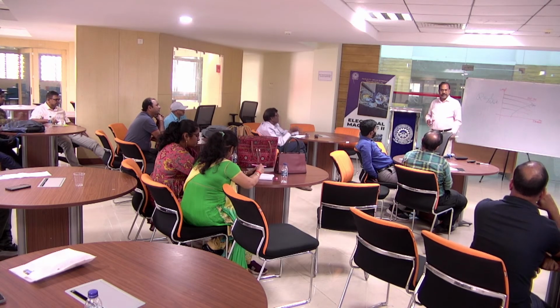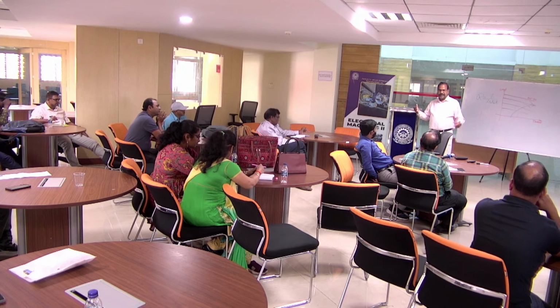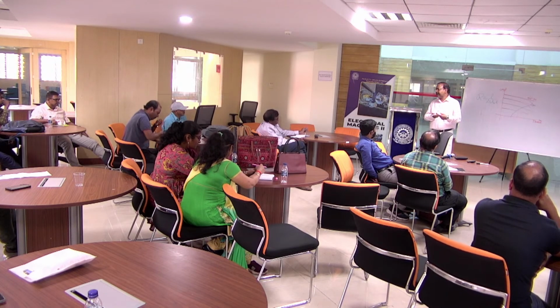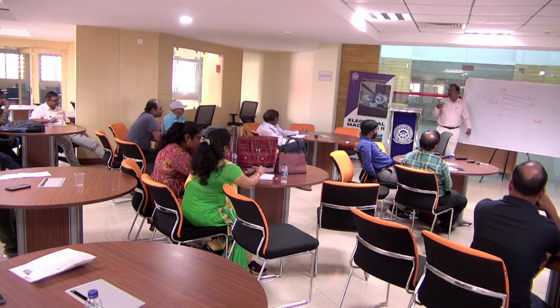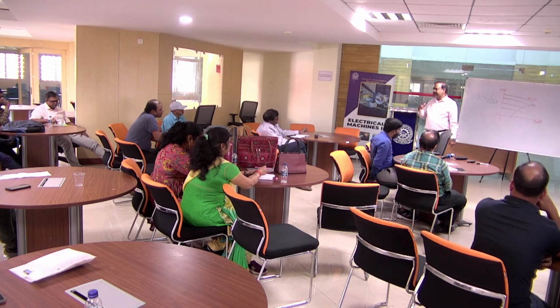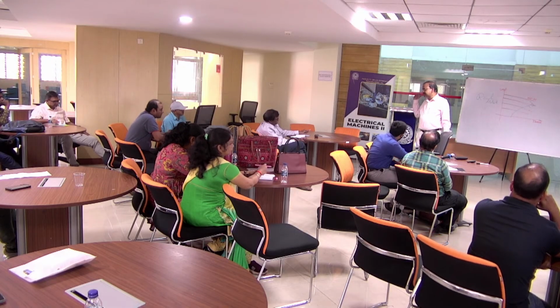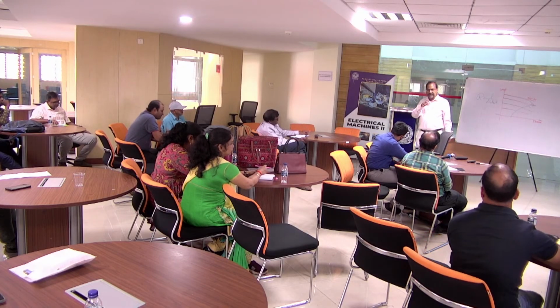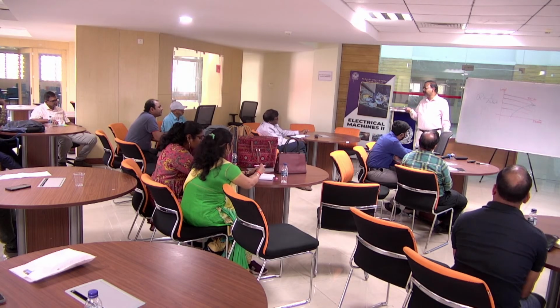So reluctance is less. But in an induction motor there is an air gap. Primary means stator, secondary means rotor. Their iron core is there, but in between they are separated by an air gap. Because of the air gap, the reluctance is more. So the induction motor takes more magnetizing current compared to a transformer because of higher reluctance. To produce the same flux, it takes more magnetizing current, and this magnetizing current makes the power factor poor.